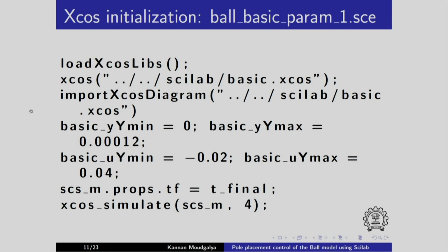After you compute it, you initialize it using this file whose name is given here, that loads this xcos file called basic.xcos. The word basic is the same thing that I have used in the MATLAB file. There it was basic.mdl.